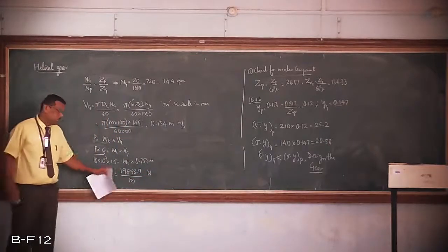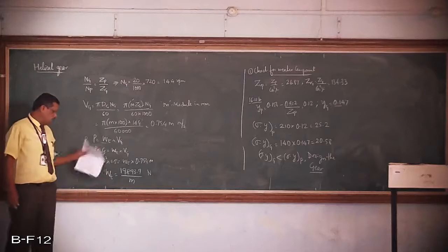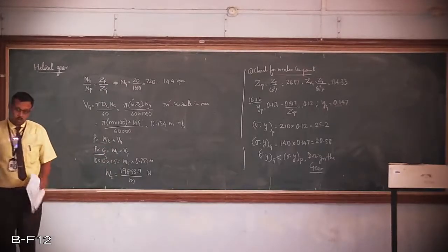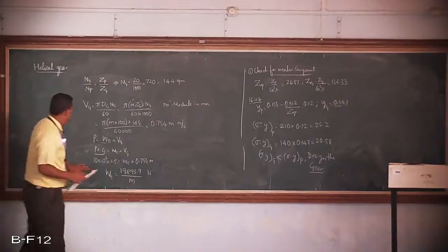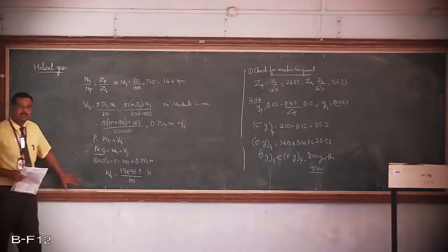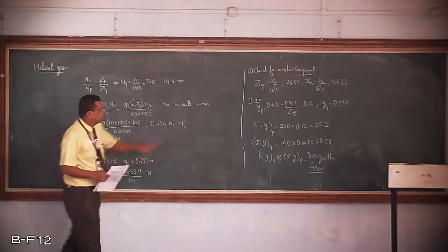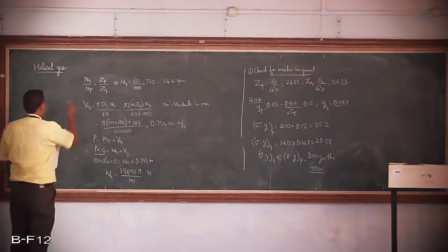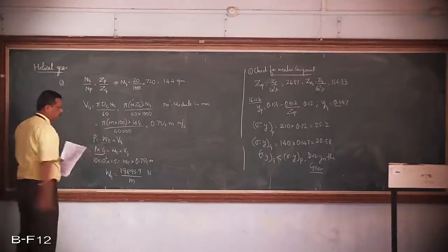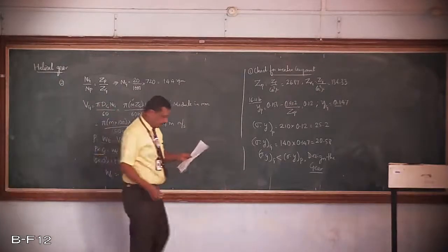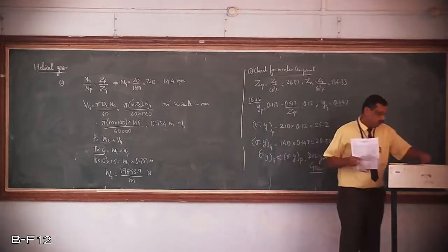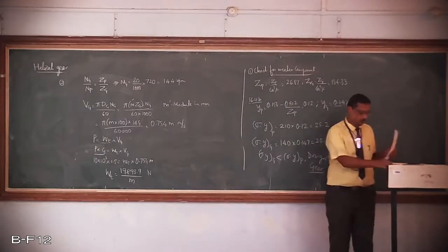Whatever tangential load you have calculated incorporates the service factor as well. Therefore, the first part is the check for the vector component, and the second is the calculation of the tangential load. This is the second step. Now, third, let us make use of the Lewis equation and try to find the dimensions.